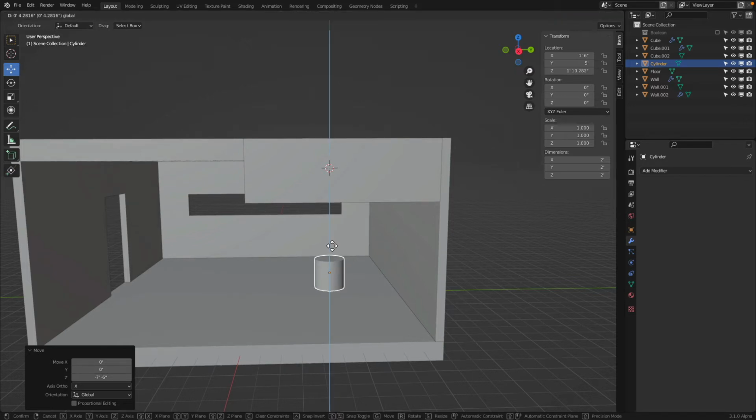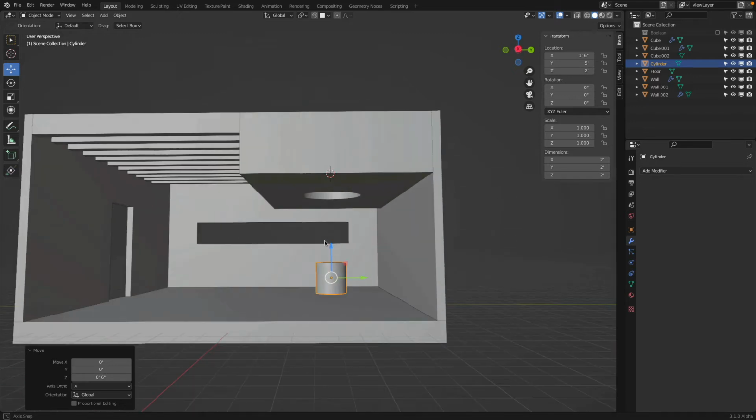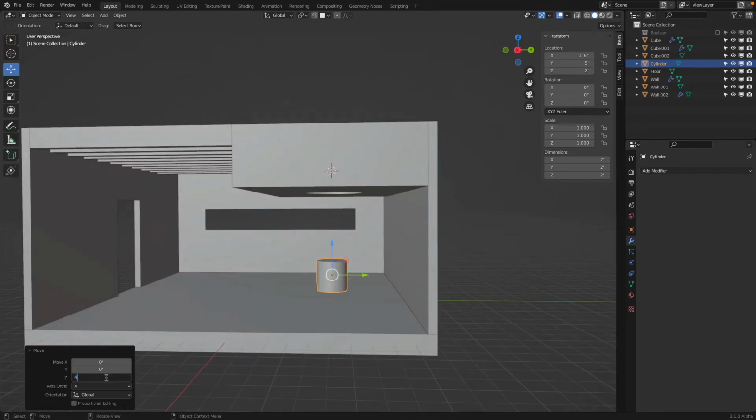I move up, and on your keyboard, like in Excel when you write an expression, you have to press the equal key. And now I can type in 6 and then the unit inches and enter. There we are. Or later here, I just do this. So I move this one up to whatever and then correct this.